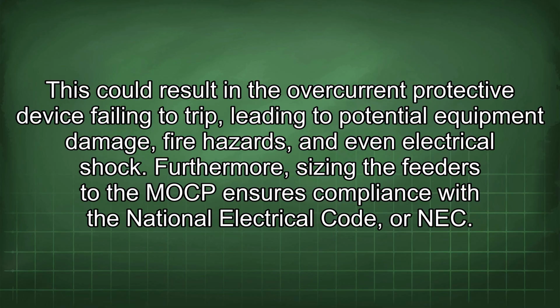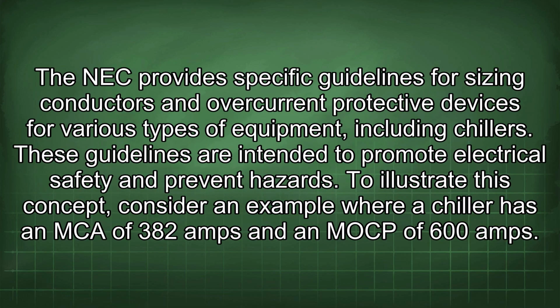Furthermore, sizing the feeders to the MOCP ensures compliance with the National Electrical Code, or NEC. The NEC provides specific guidelines for sizing conductors and overcurrent protective devices for various types of equipment, including chillers. These guidelines are intended to promote electrical safety and prevent hazards.